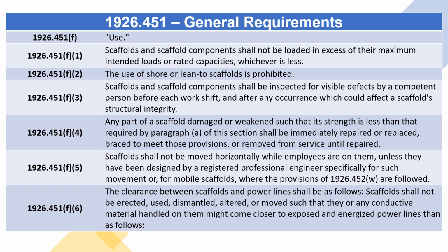1926.451(f)(2): The use of shore or lean-to scaffolds is prohibited. 1926.451(f)(3): Scaffolds and scaffold components shall be inspected for visible defects by a competent person before each work shift, and after any occurrence which could affect a scaffold's structural integrity.